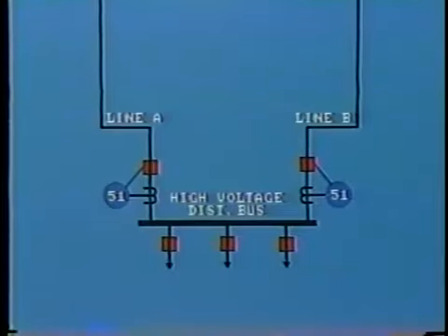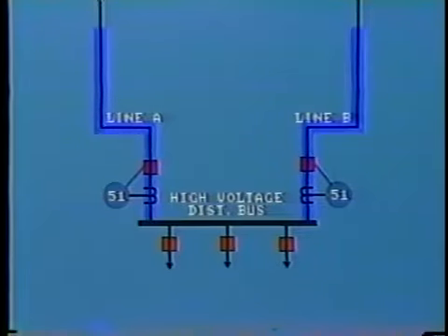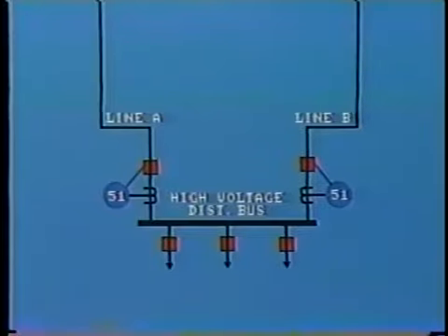This example shows the high voltage bus in a distribution substation. It is fed from sub-transmission lines which are part of a continuous loop. In this arrangement, current may flow in or out of either sub-transmission line, depending upon conditions or system configuration in other parts of the loop.